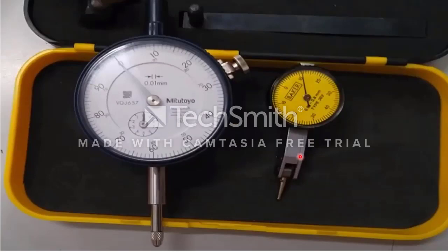Okay, and this is the bezel, which you keep at 0. As it can move up and down, it is called a plunger type. This is the contact point, this is the dial, this is the dust cap, and this is the revolution meter. Anti-clockwise this will be rotating, and this will rotate in the clockwise direction, based on the forward or backward movement.